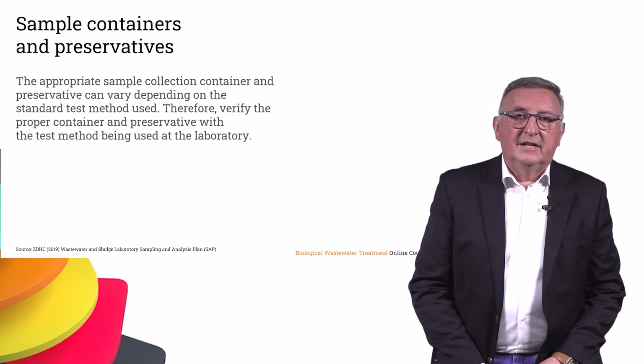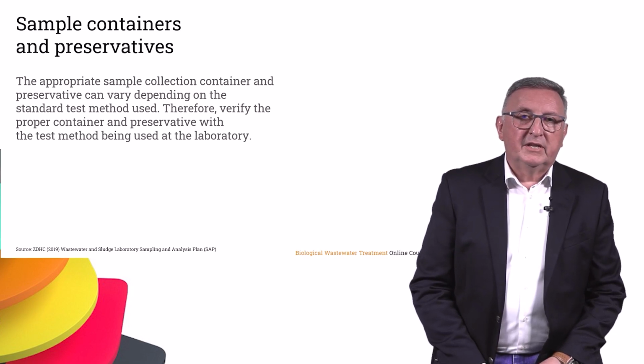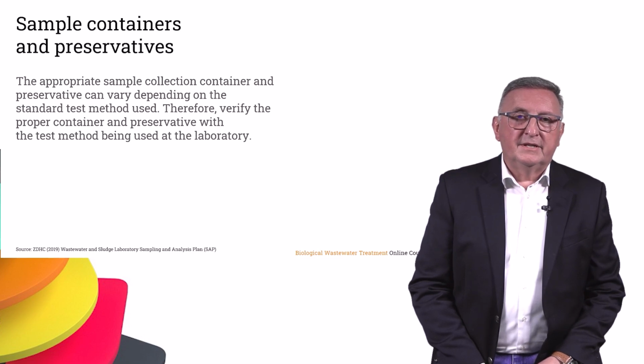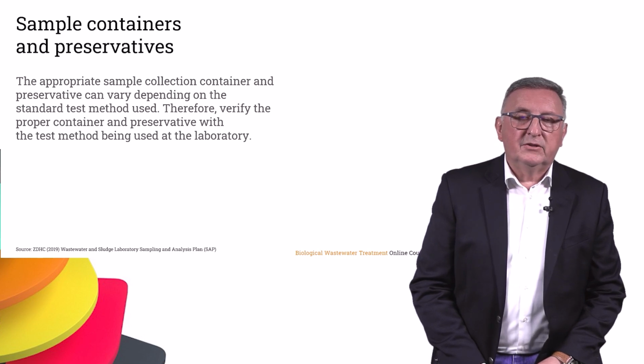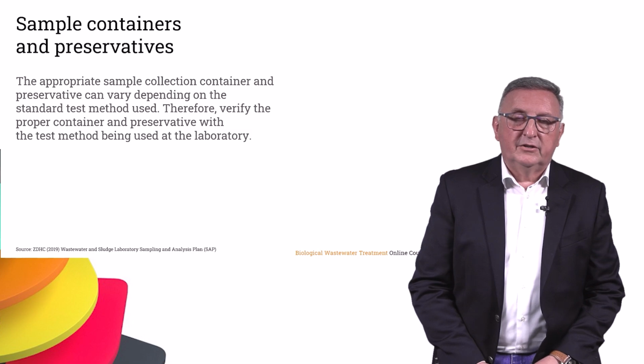Sample containers and preservatives are very important in the whole procedure. The appropriate sample collection container and preservative can vary depending on the standard test method used. Therefore, verify the proper container and preservative with the test method being used at the laboratory.